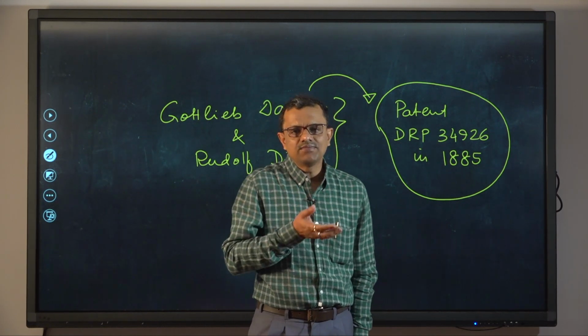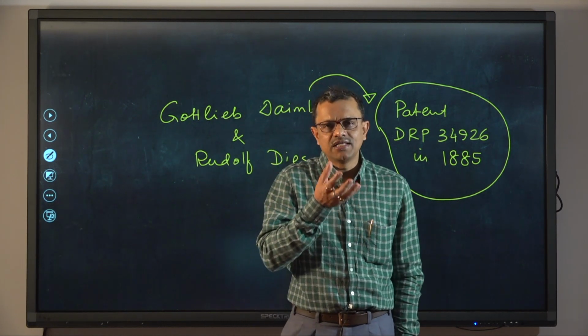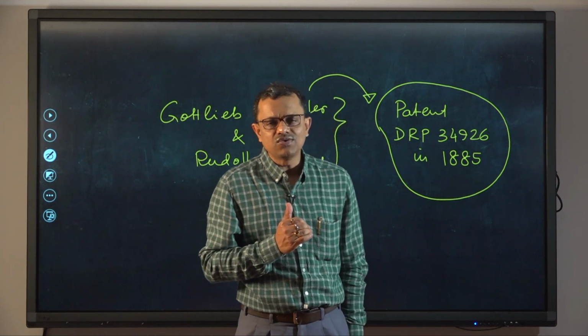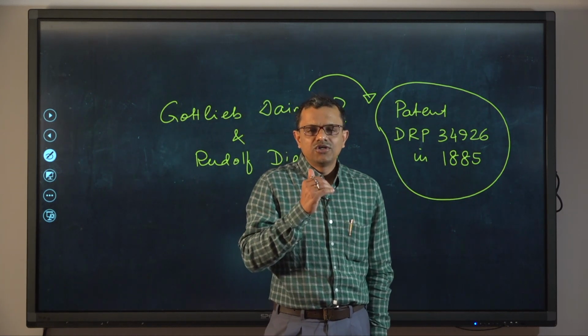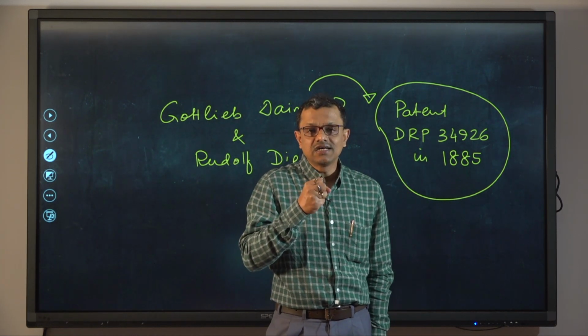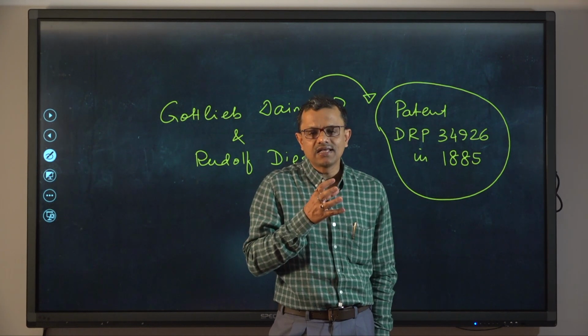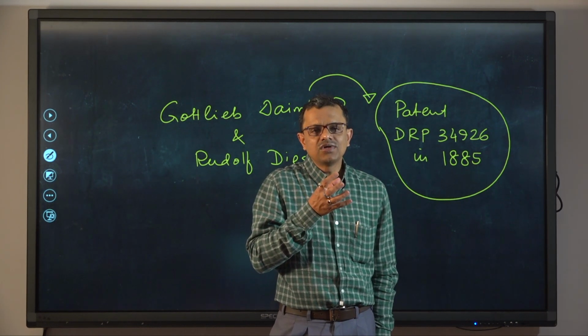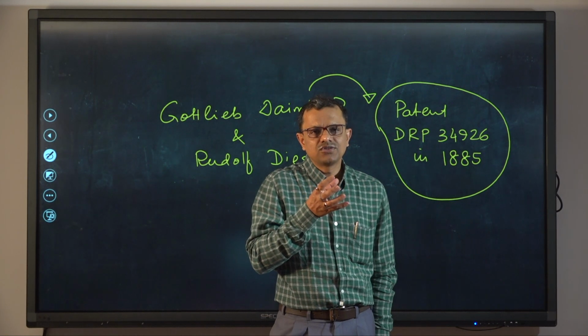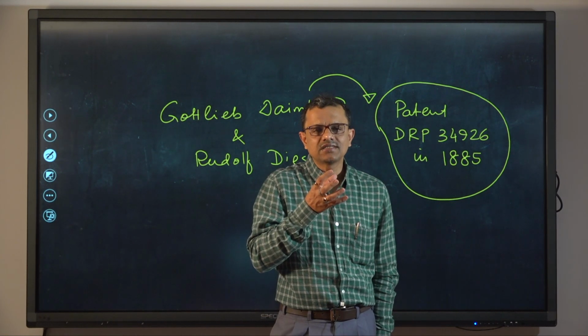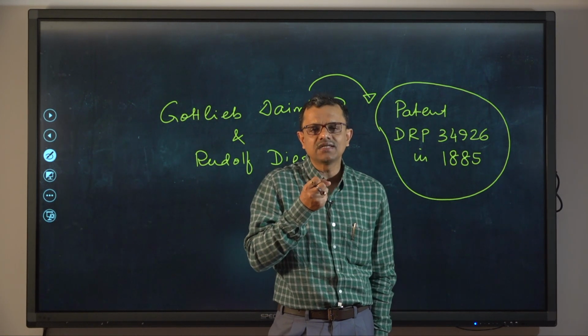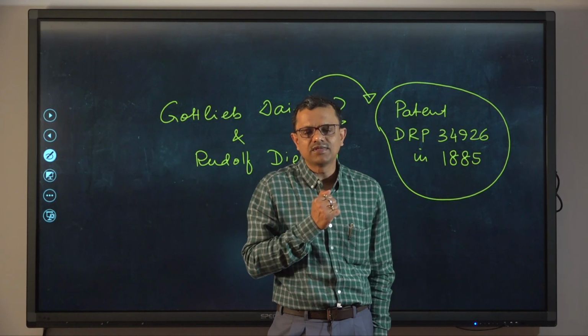But at the bottom end of the piston, if we can use the downward movement of the piston to compress the charge, that means if we have a cavity in the crankcase and we allow charging of mass through the cavity of the crankcase, that compression can be done by the downward movement of the piston.